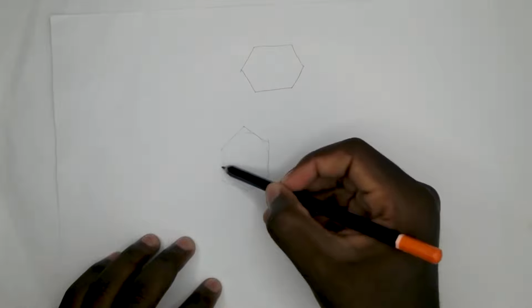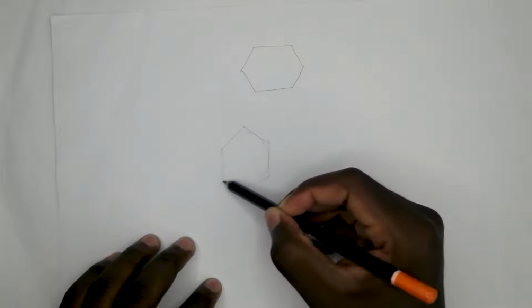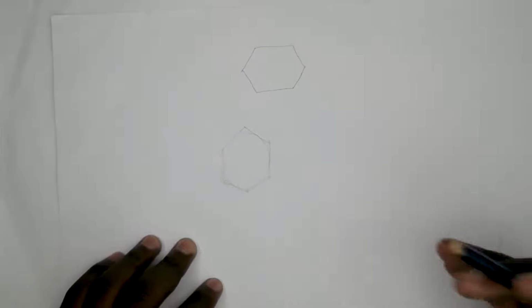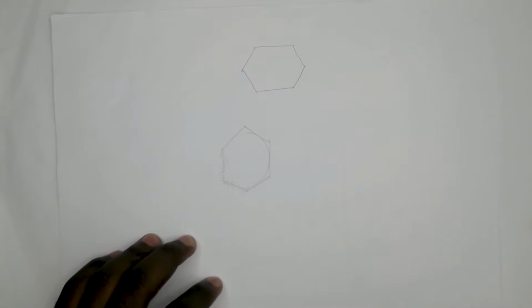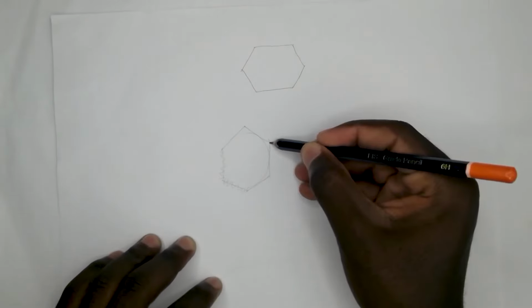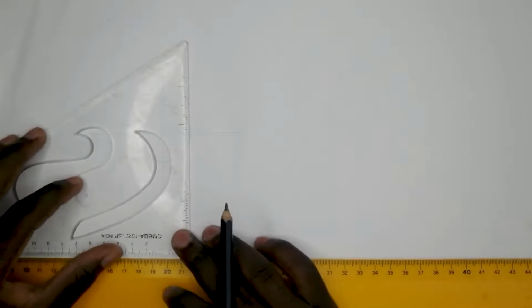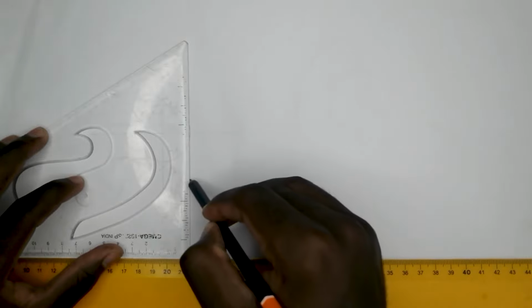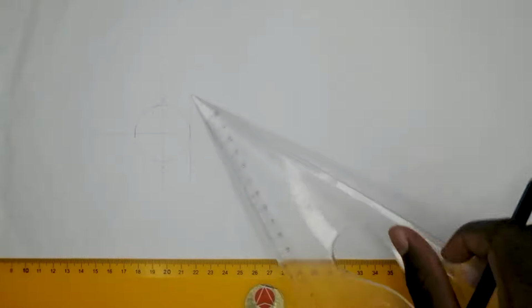So these two sides here are not part of our drawing, but when analyzing, we should really see them. So the easiest is drawing this side. The first time we draw it, because we don't know all the sides of our hexagon, we're going to just draw it in construction pencil. So we'll draw it like that, construction pencil. Make sure this line is at 90 degrees with this other one. The easiest way is to use your T-square and your set square.